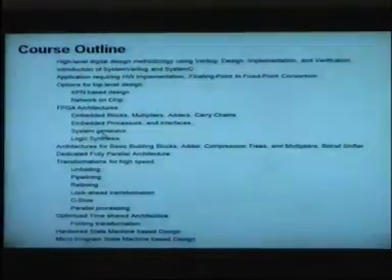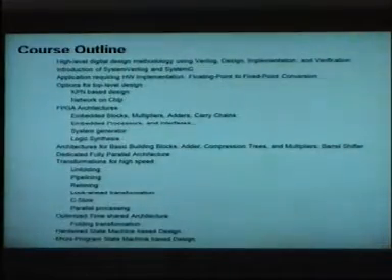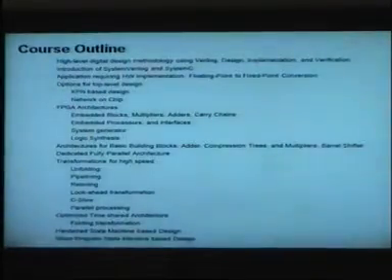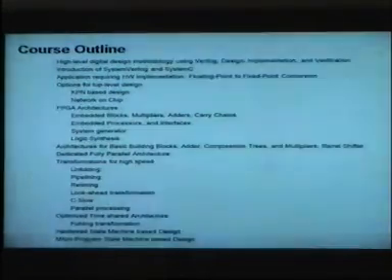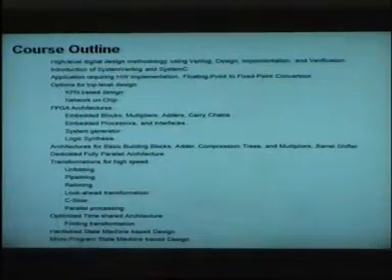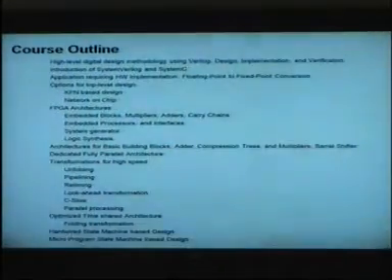And then there are tools, and the tools are like System Generator, which can help you to do most of your work. If you are in a professional setting designing something, there are things which you can just design by automatically generating the Verilog code. So there are cores which you can design, the blocks which are already there. So we need to know all the resources we have, and then how best you utilize those things. What are the issues in logic synthesis once you are actually writing Verilog code and synthesizing it.